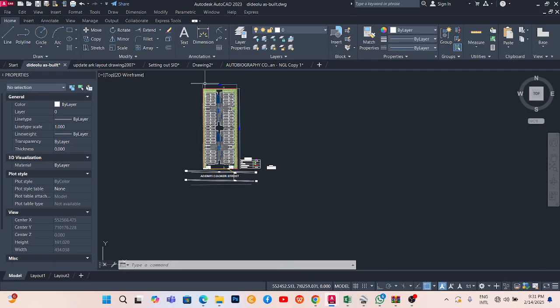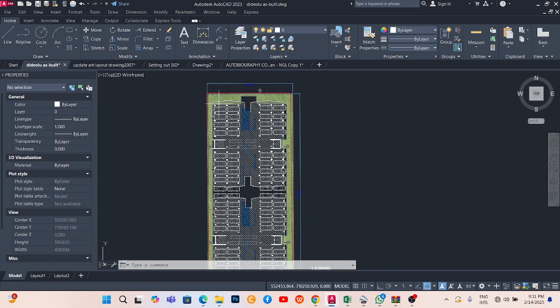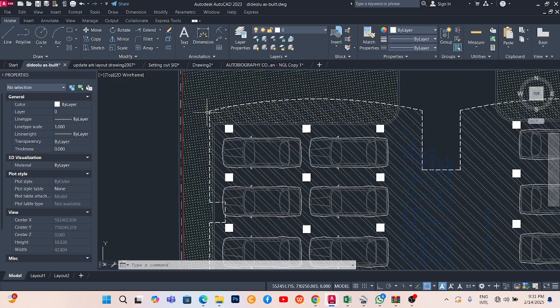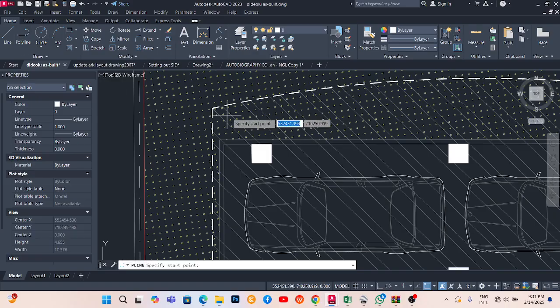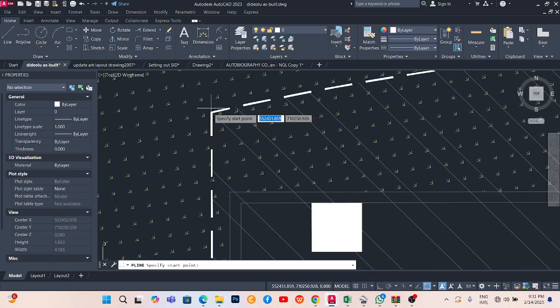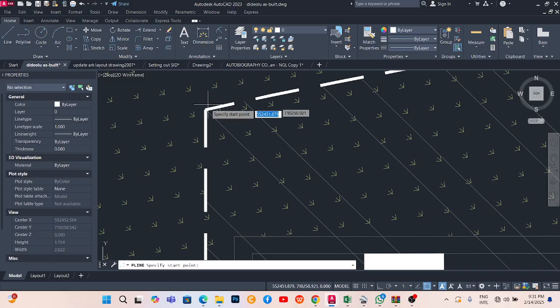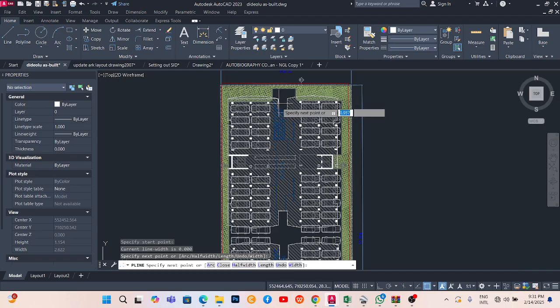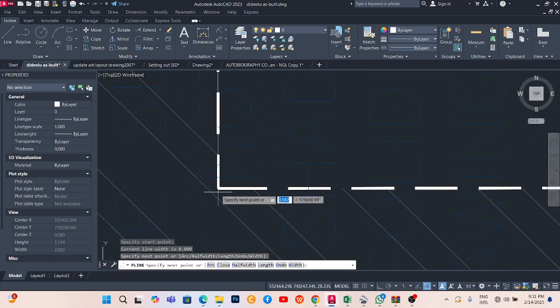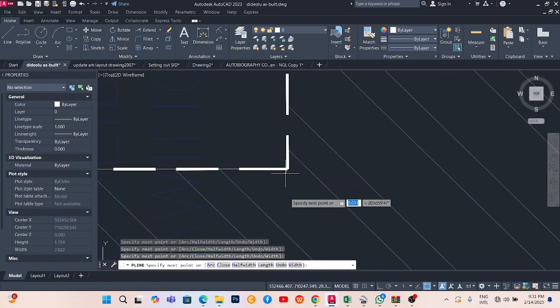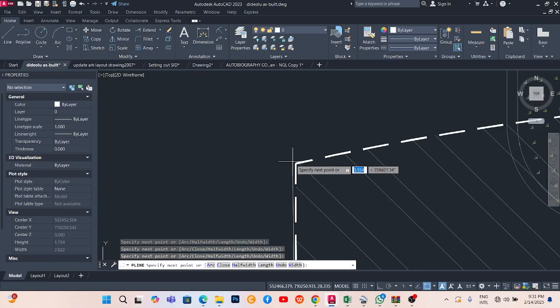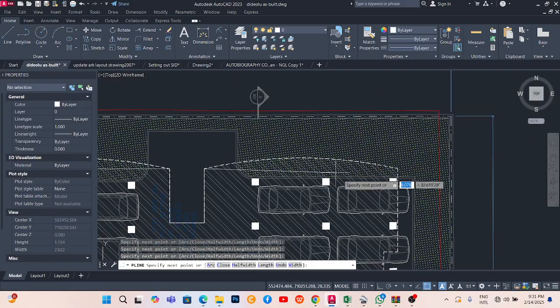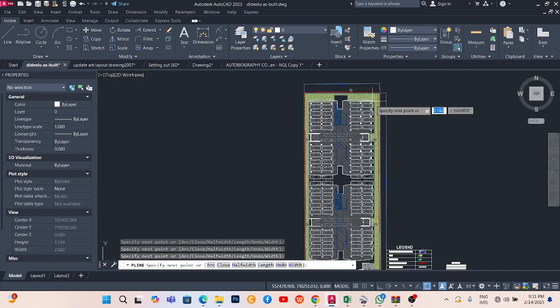So that's how to superimpose. Once this is done, or let me say I superimpose the structural, for example, I can easily pick these points. I will just press my polyline. If I have multiple points that I want to set out, I will just click my polyline. Let's assume that I want to set out the building footprint. I will click the polyline from here, use it to pick the edges to here, then maybe this, maybe this. Let's leave this curve for now. So maybe this, then go straight down.